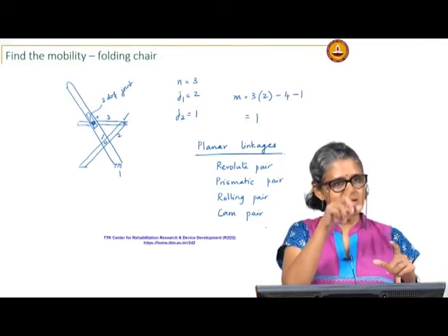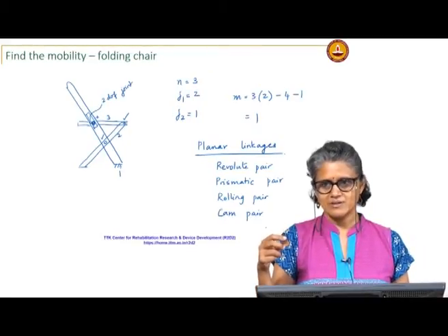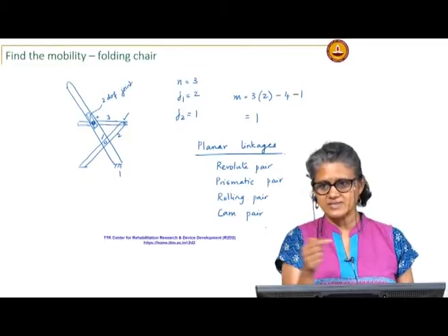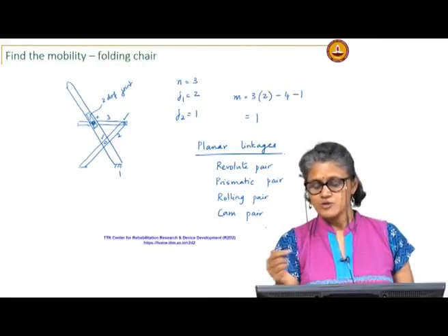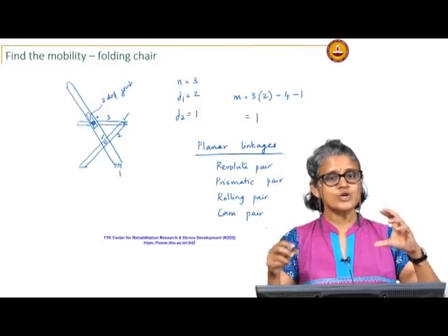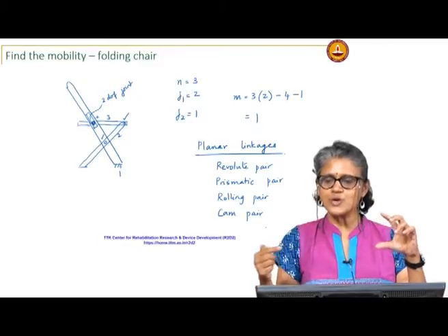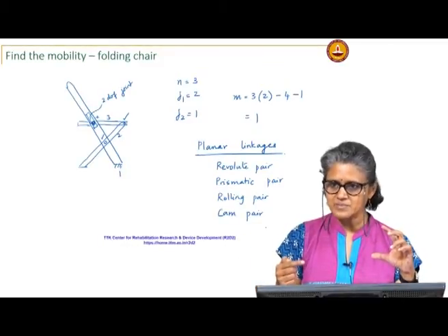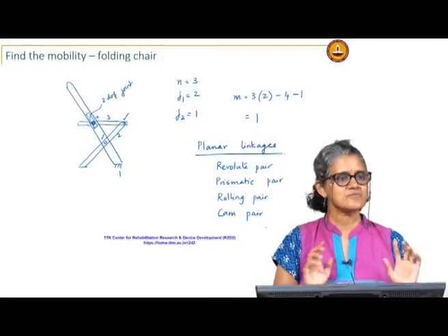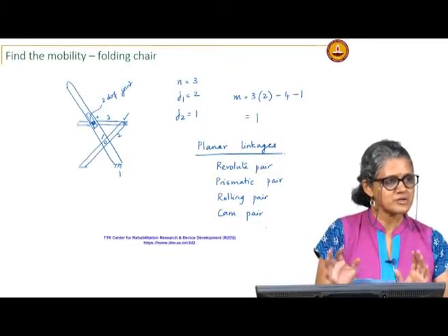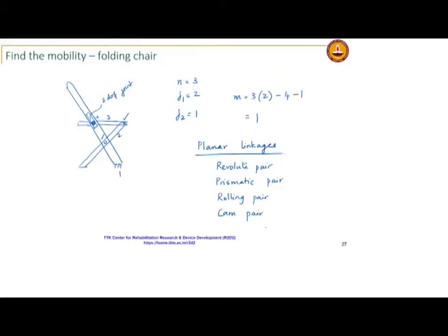So, the pliers, if you look at it, it is essentially a 4 bar linkage, but you will have one screw joint here which will basically adjust one of the fixed pivots. So, it can change how it grips, the gripping. So, that screw joint you would not consider as part of the mechanism itself, okay. That is a separate thing that is used only to adjust this planar mechanism. So, even though the joint exists in the planar mechanism, it is not part of the kinematics of that 4 bar. So, you have to be able to differentiate between which joints belong to the mechanism that you are analyzing.